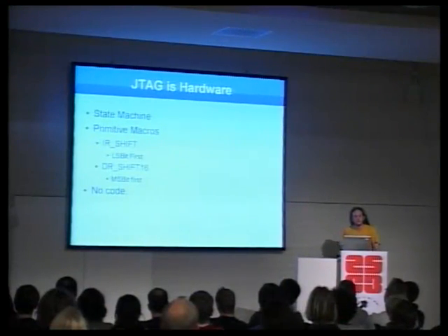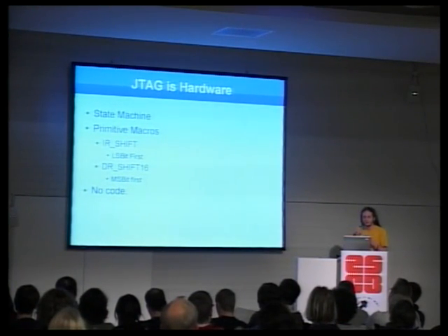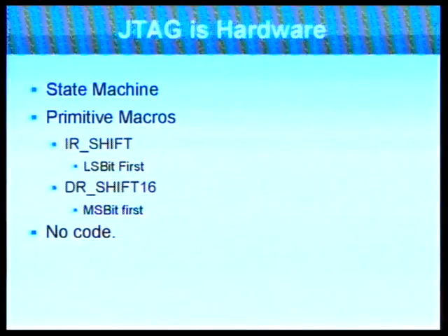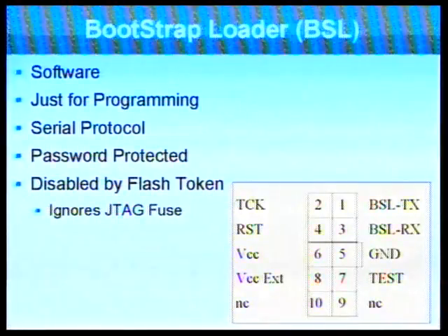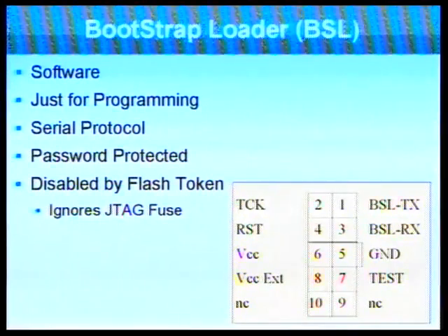But this is all implemented in hardware. You have an actual state machine. You shift into registers, and you shift out of registers. And there's no software implementing this within the chip. An alternative is to use a bootstrap loader.